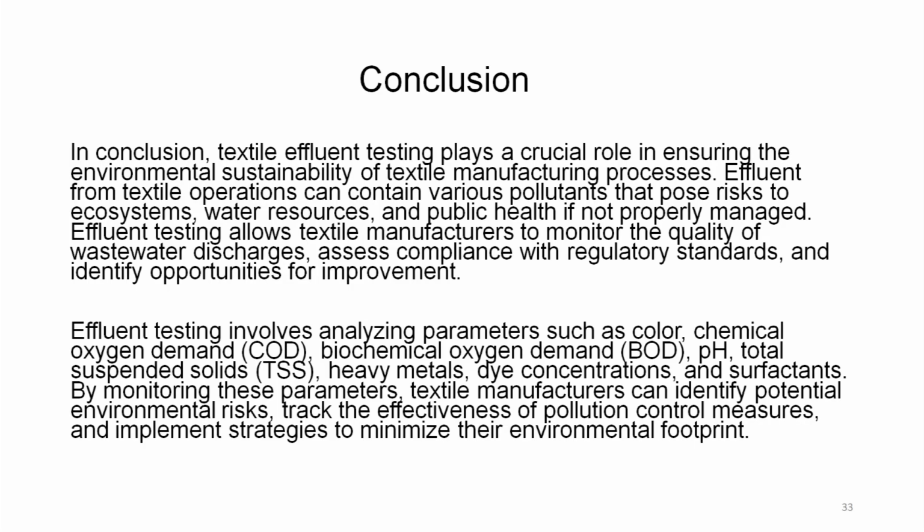Effluent testing allows textile manufacturers to monitor the quality of wastewater discharge, assess compliance with regulatory standards and identify opportunities. And as I had already mentioned, effluent testing must involve color, COD, BOD, pH, total suspended solids, heavy metals and dye concentration in analysis. Then only we will be able to minimize their environmental footprints by strategizing a good remediation plan.